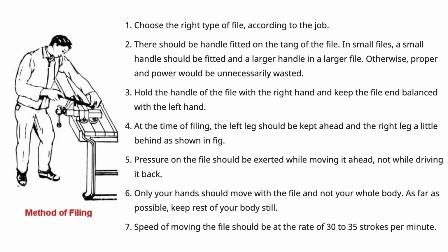So there are different ways of using the file. Precautions should be taken, like selecting the file according to the job. Do not use a file without a handle of the right size. The handle should be fixed on the file. Without a handle you cannot deliver proper force and control, and you may get hurt. A new file should be used on a soft metal first, and then on a solid metal. If substantial material is to be cut, then first chipping should be done and then filing.